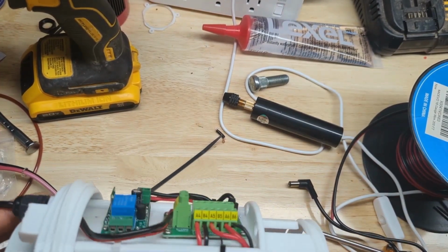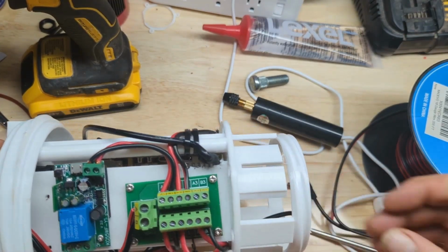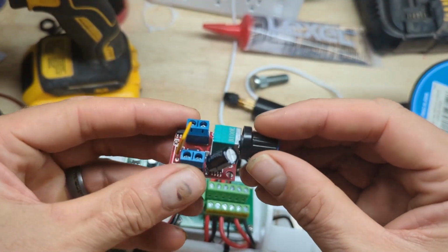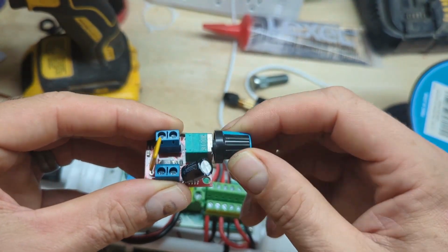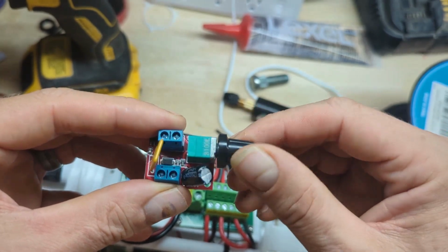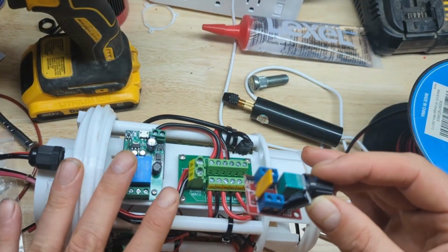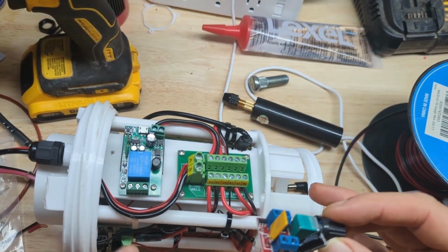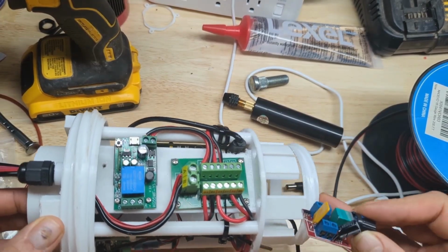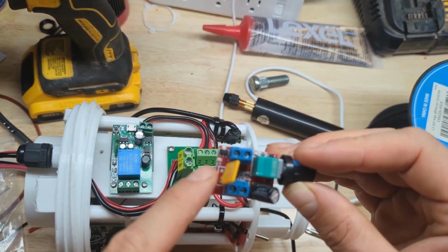Now the last component to hook up, and it will go right here on this A3B3 to get its power, is our PWM controller. So you'll recall this is the device that actually controls how much power we send to our dew ring, because we don't want to have it wide open because we don't need that much power going to the dew ring. The enclosure itself, all the components inside of it will generate its own heat. Just with the Pi running, any of the electronics running will generate heat. So some heat will already be there traveling up to the dome, but this will just add supplemental heat with our dew ring.